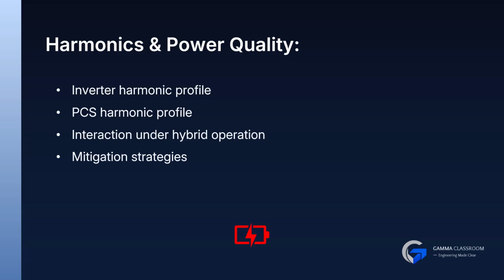Inverters generate harmonics due to switching behavior. Excessive harmonics can cause overheating, misoperation of equipment, and non-compliance with IEEE 519 limits.